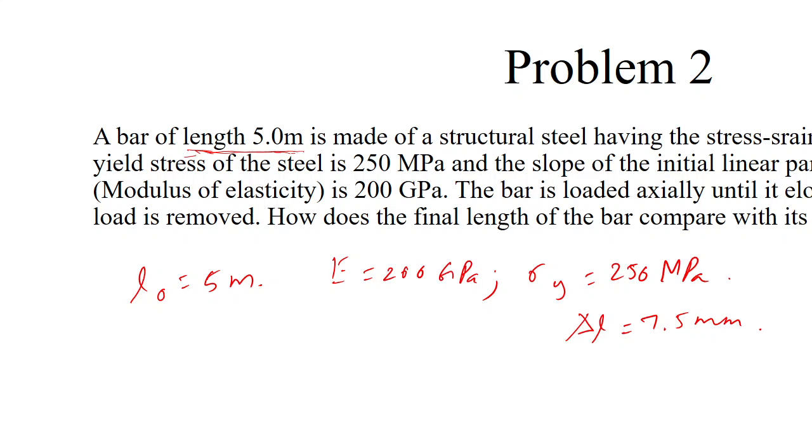Actually, there will be some elastic recovery, and then you will be getting a different answer. Sir, we have to calculate the residual strain, right? Yes, we have to calculate the residual strain, and based on that residual strain, you have to multiply this with the original length of the bar, and then calculate the final length. Sir, 1.25 mm longer is coming finally. Yes, bro, that is the right answer. Anyway, we will work it out here.